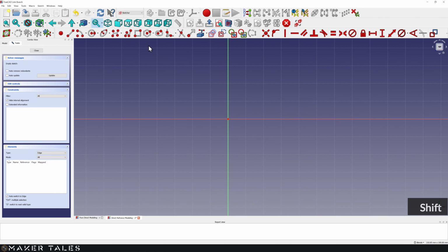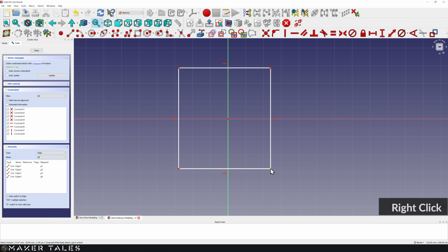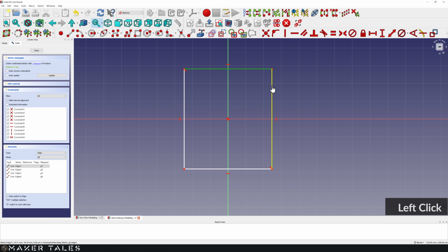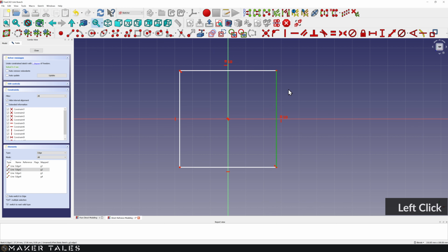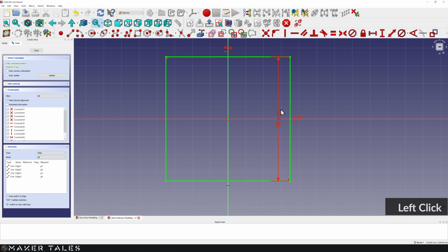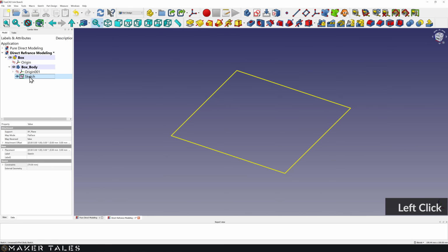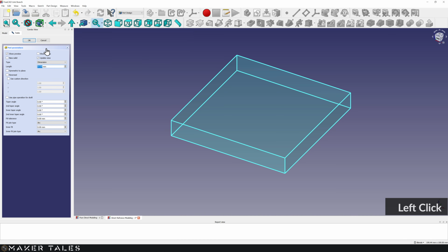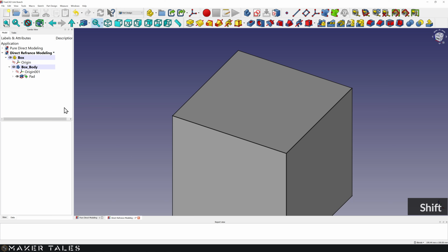And this is pretty much the same as last time. We're going to create ourselves this rectangle, make everything center symmetried once again. So we'll go these three, press S, these two, press E. Then we're going to add our dimension to this line with Shift V, and we'll go for 70. Click OK, pretty much everything exactly the same so far. Click close, and we'll rename this.